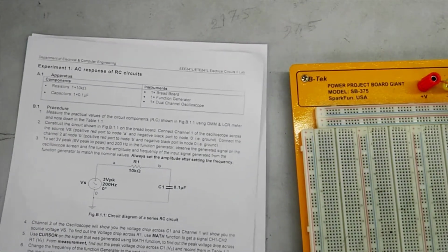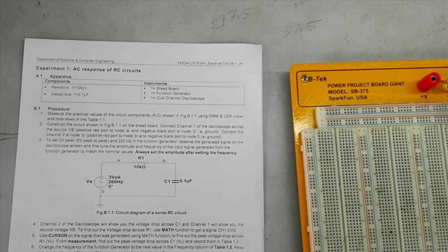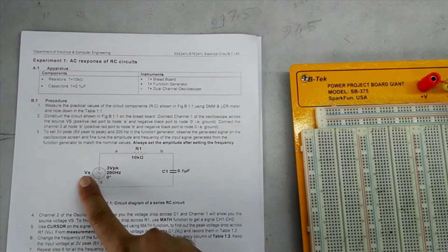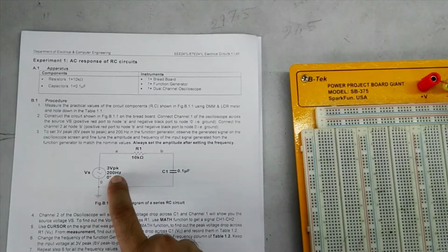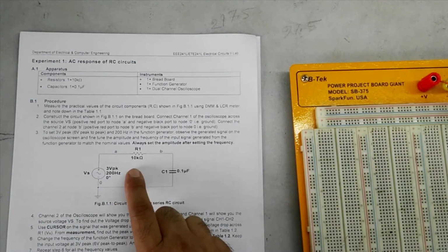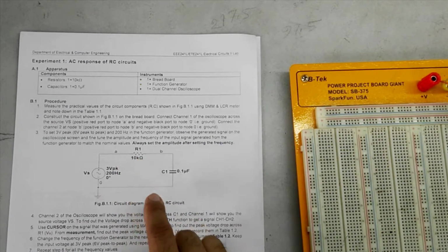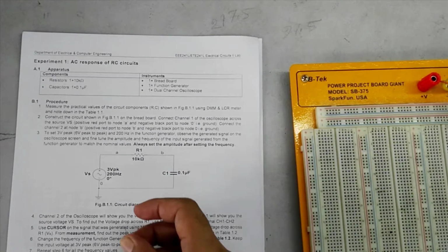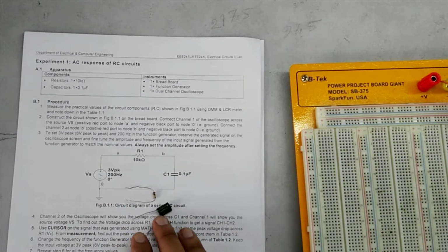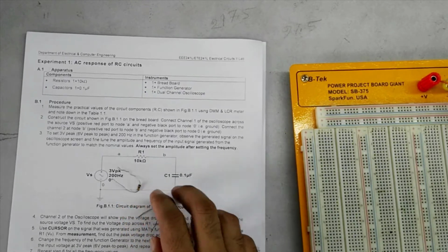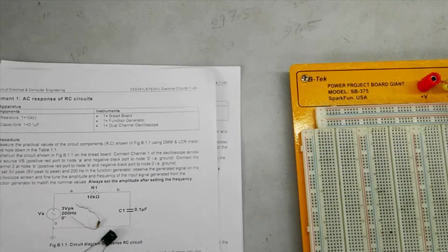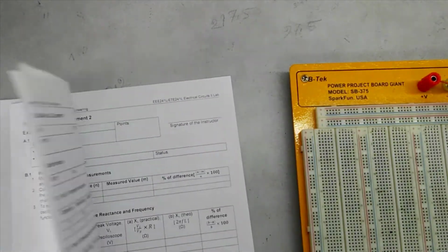So first let us consider this RC circuit, where we'll analyze the response of an RC circuit. We have a source of 3 volt peak and initial frequency of 200 Hz, and we have a resistance of 10 kilo ohm and a capacitor of 0.1 microfarad. The components that we will use are these resistance and capacitance. So we will connect this circuit. If we look at our data table for this experiment,